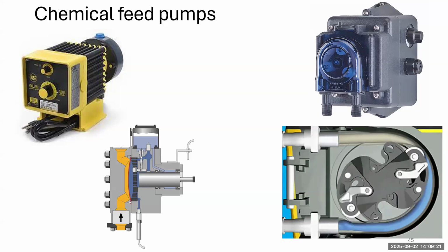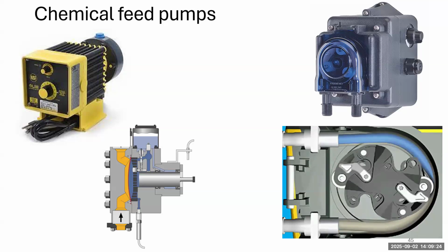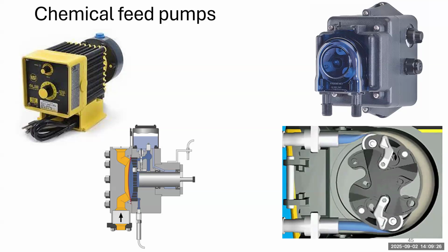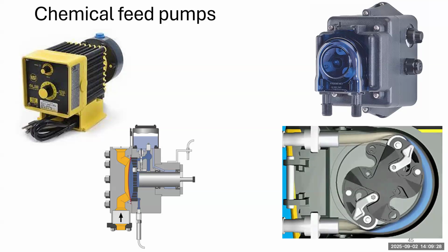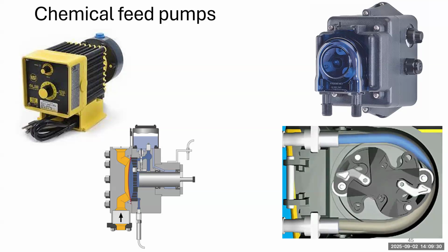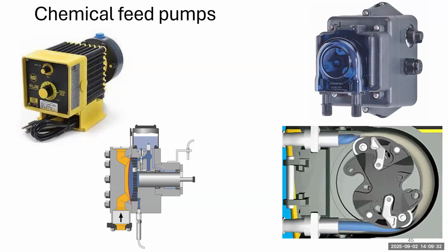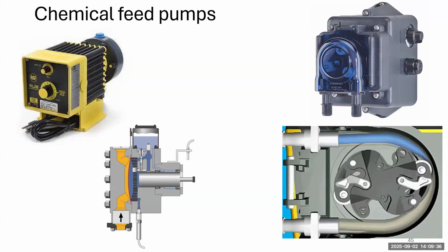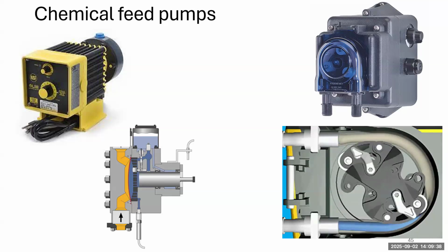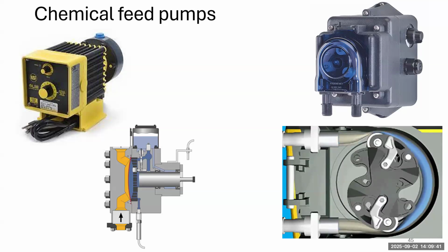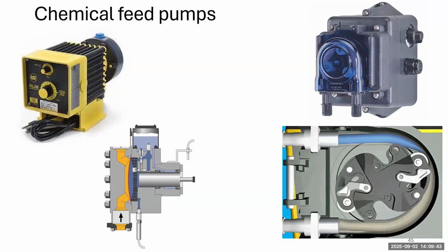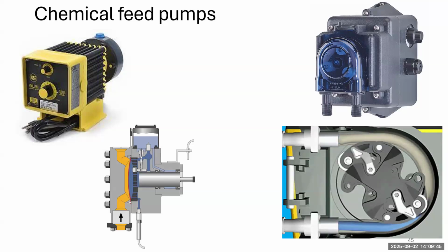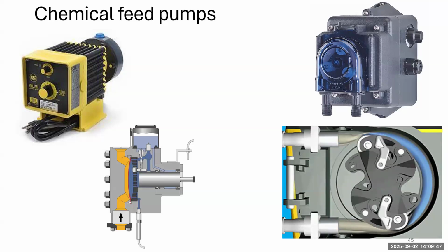We had a peristaltic pump at our wastewater treatment plant instead of the water plant, but eventually it will wear out. It's kind of a weak point right where the tube connects to the piping and where the roller hits, and it will eventually wear out. You can see the wear and then kind of rotate the tube to make it last a little longer, but eventually you have to replace it.